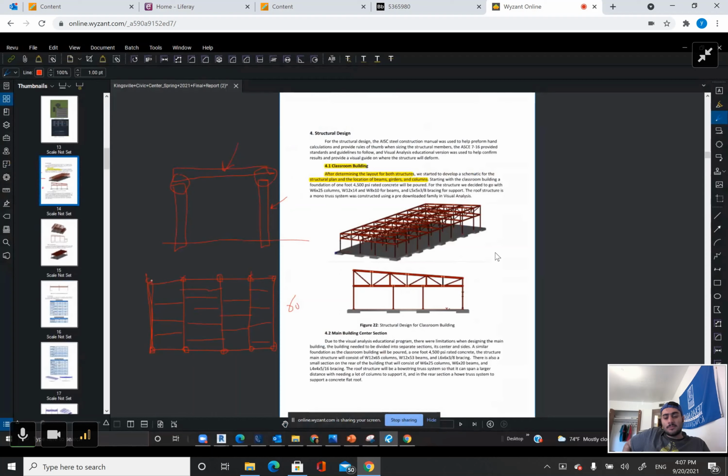Do you mean the slabs? No, I'm just drawing a roof plan for a generic building. I want to explain that sometimes you might have these main beams, and sometimes you might have secondary beams that are filling the space, because you want to be able to fill a space for you to pour a concrete slab. Well, here in the US, they call these big beams girders, and the small beams are still called beams. Okay? So what he did here, he located the beams, the girders, and the columns. So this is really what he's talking about.